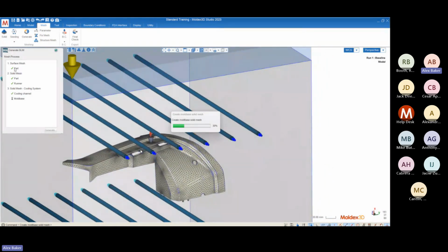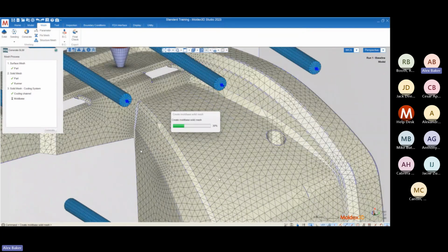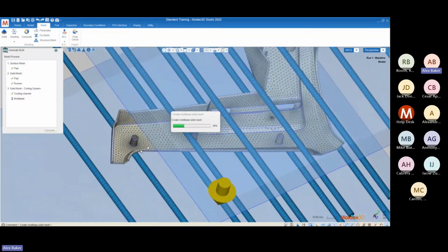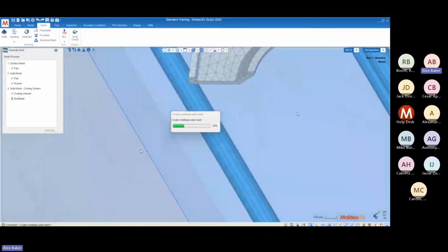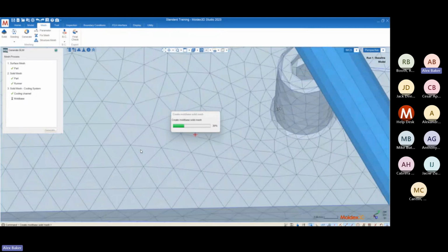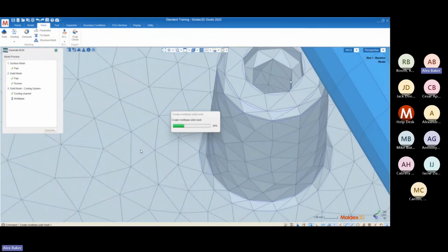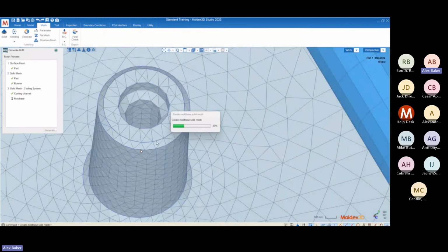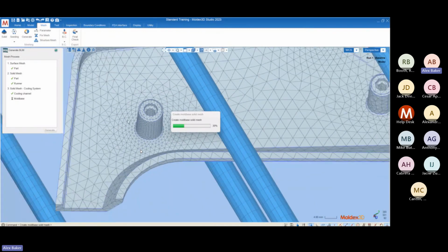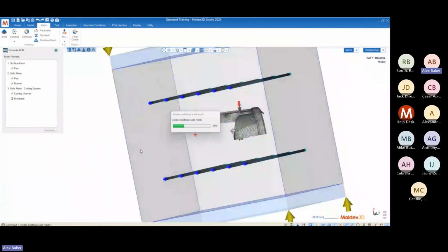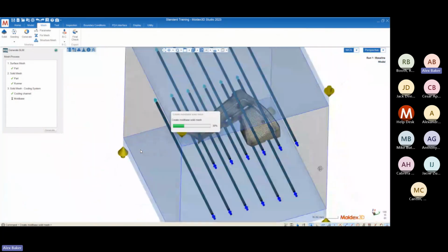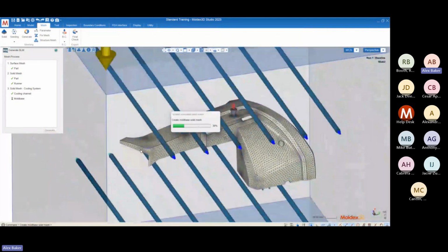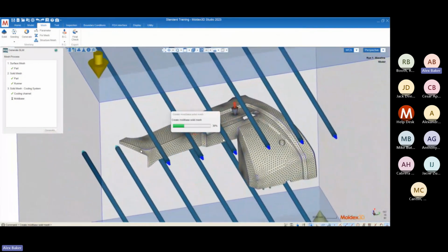Now the mesh that's created here, we get our surface mesh, which again looks like a bunch of triangular surface mesh elements. We go to the bottom here, we can see that refinement take hold. We see 6 nodes. We see that hexagon around the middle of this boss that I did not refine. You can see that refinement actually does clean up that feature quite a bit. The 5 layers BLM is going to be created through the thickness of our parts, which we don't see here. We will break open the mesh to see that in just a moment.